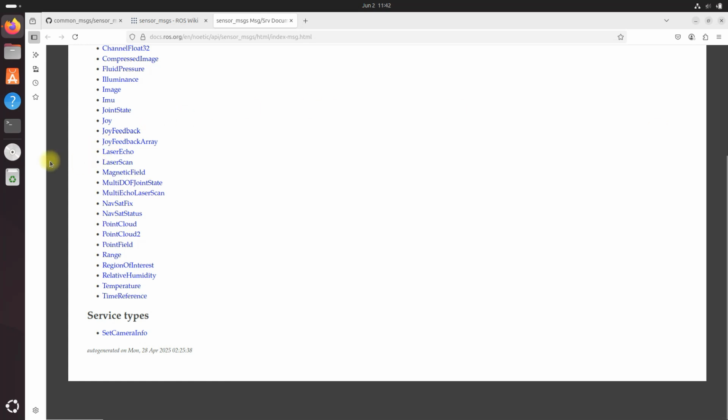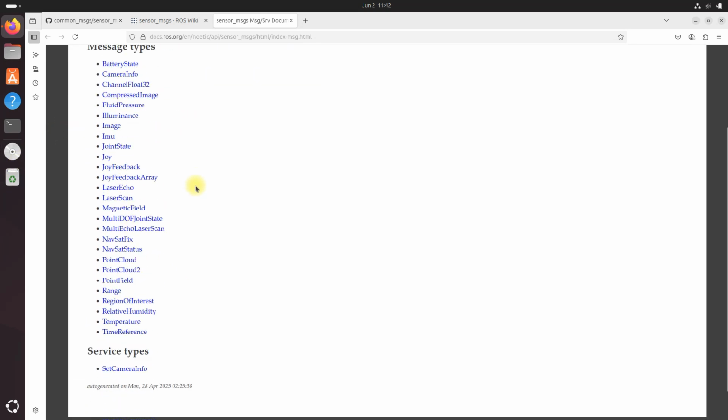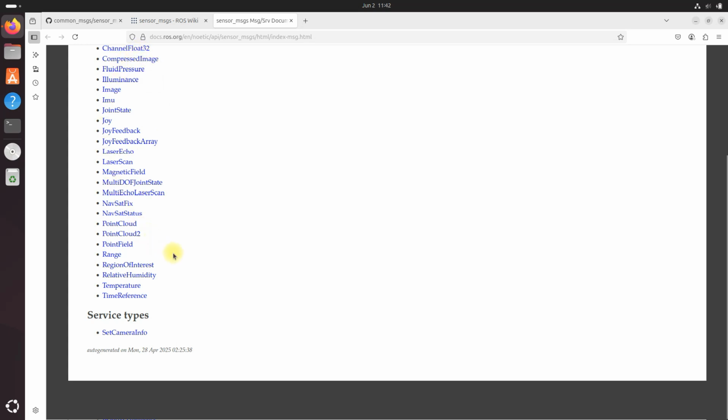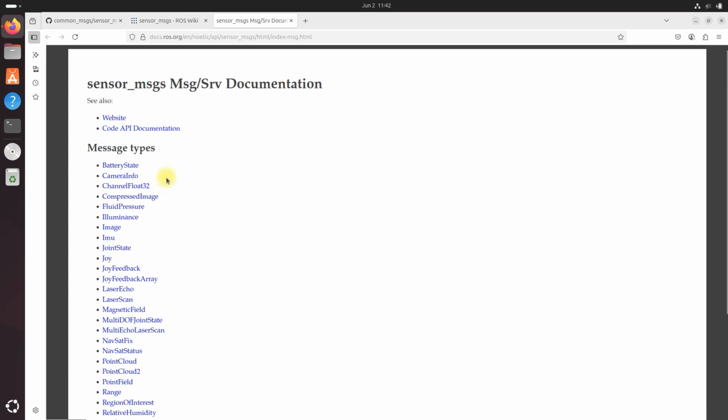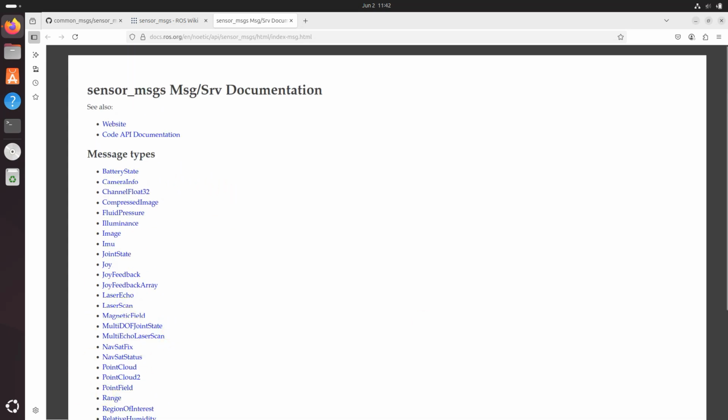That's really cool because even if different companies have different drivers for their different hardware, to make their sensors compatible with ROS2, they'll make sure the publisher of the data conforms to these specific sensor message types, which are pretty much the same from ROS1 to ROS2. It's not been a big amount of change. So you can use any sensor as long as it speaks this common language.